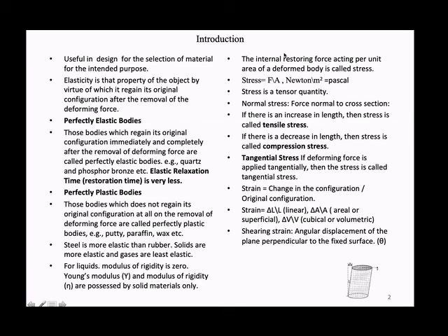Now, what is stress? The internal restoring force acting per unit area of a deformed body is called stress. Suppose I apply a force and the body resists the force, then stress is developed. If it won't resist the force, it will simply deform, and there is no stress developed in the body. So only the resistance to the external force developed by the body puts it under stress. So stress is equal to force per unit area. The SI unit is Pascal, Newton per meter square.